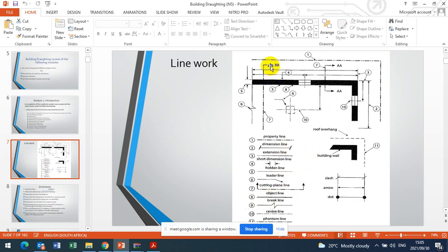What else is here? Cutting plane, you can see the cutting plane line should be under this layer. We know the cutting plane line. This square that you see here is a column. It's a square pillar. Usually in drawing, we measure from the fixed pillar. You see the dimension here, though they didn't put it. You can use the center, the grid lines, we call them. You can use the grid line to measure to the inside of the wall. Or from here to there, you can measure, because it's a fixed fixture.